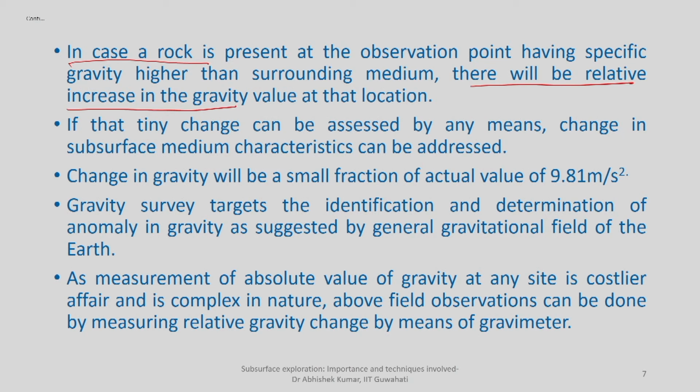Why is there an increase? Because you have a rock medium which is not supposed to be there, or which is adding some kind of heterogeneity, and having specific gravity significantly higher than the surrounding soil medium. So, because of any external, foreign material with higher density, it is going to increase your density or specific gravity, or the gravity itself.